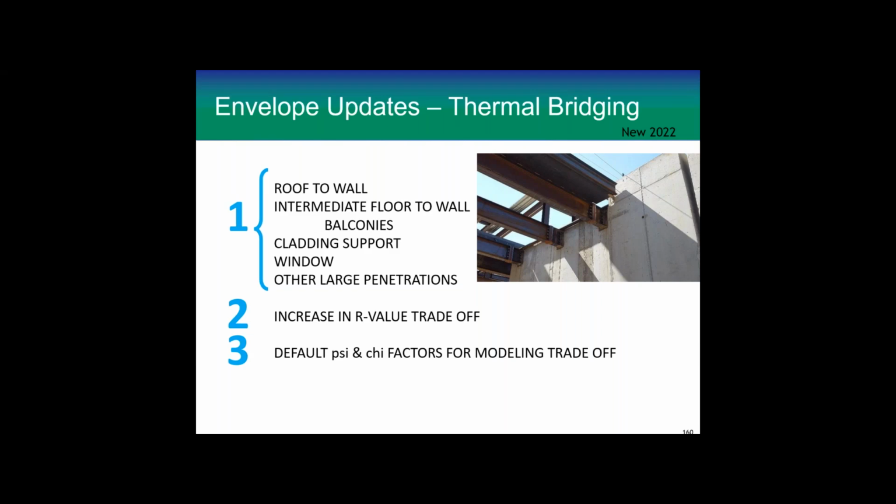And then there's the PSI and CHI factors. The PSI is for a point thermal bridging. The CHI is for a linear thermal bridging, and those factors are defined so that you can use them for modeling and doing your calculations.